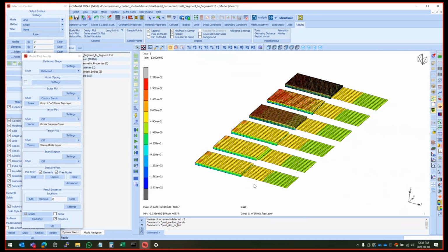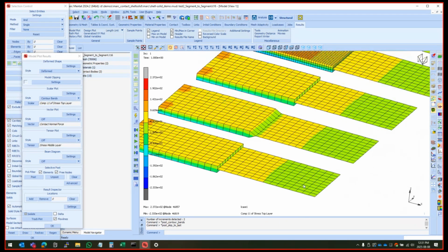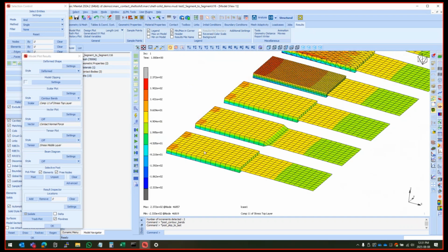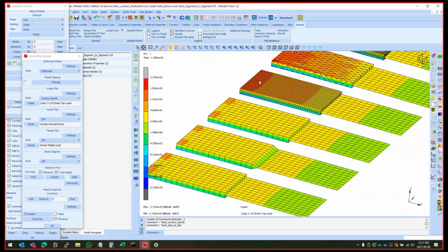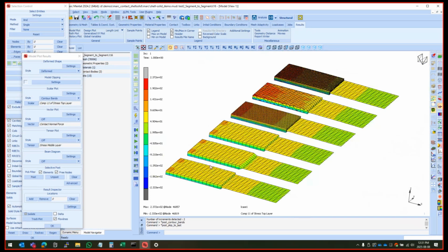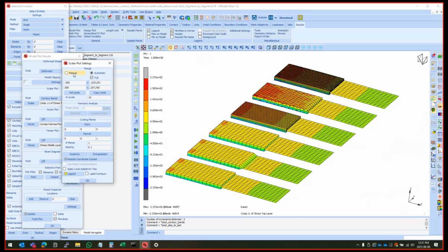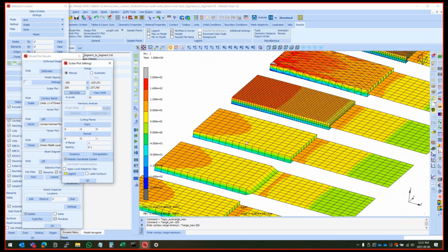Yeah. Now we have a near constant stress in that direction. And just at the back, there's a bit of a variation. I changed the numbers a bit, so that has got that kind of a pattern. The stress is lower because the element is less accurate for the mesh density we've used, so let's try minus 200 up to 200. Yeah, we still see a bit of that pattern.